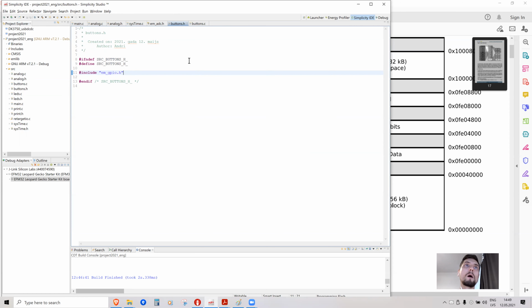So of course, we will need a function, void buttons_init(void), something that initializes buttons, turns on their pull-up resistors, attaches an interrupt to them, and so on. So buttons_init is, of course, a necessary function here. In order to initialize buttons, we will do the following. We need to set buttons as inputs with pull-up resistor.